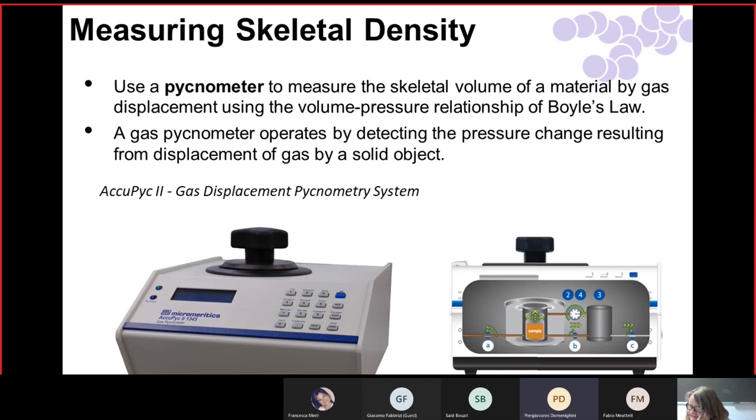Is there another question? I would like to know, I've understood that in some way the pore structure will change the properties of the aerogel. But can you choose the porosity, the open pores or the closed pores, while you are making the aerogel with the sol-gel conditions? Yes, somewhat. You can certainly control the amount. You control the density and the pore volume to some degree.